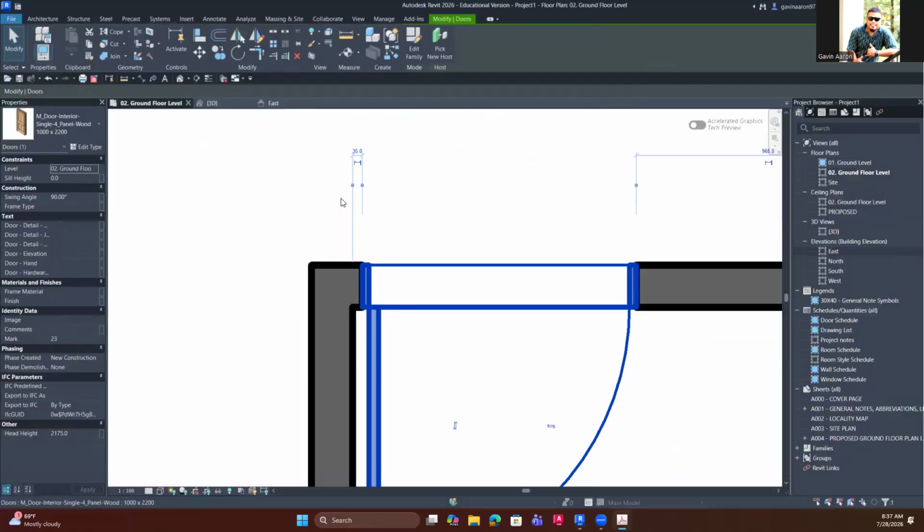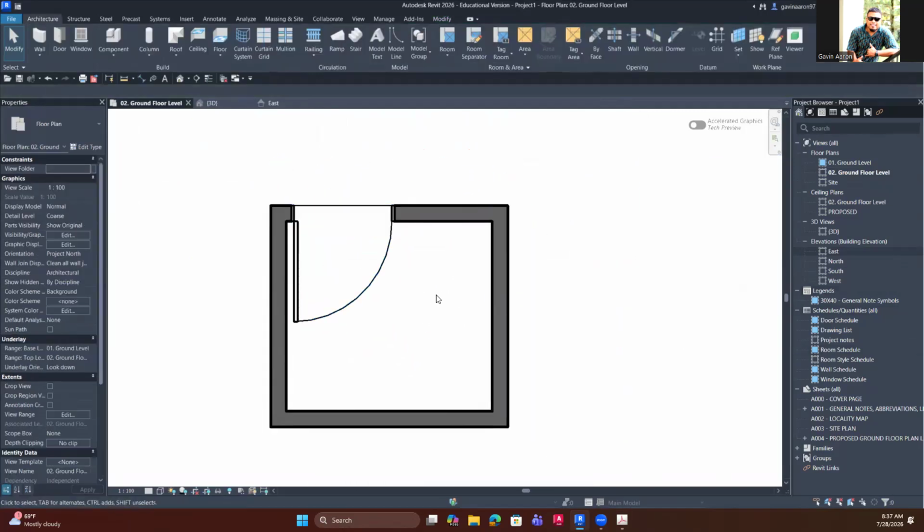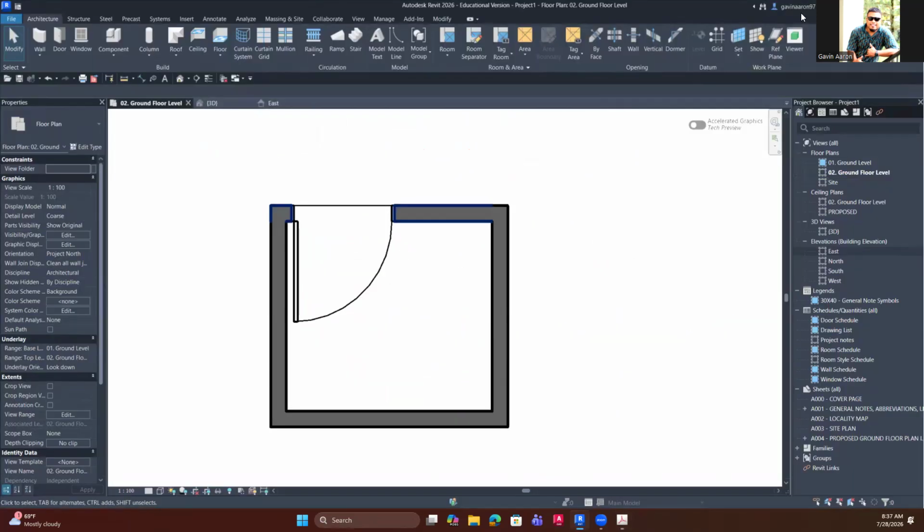So we can select this door, then you see that our door, it's offsetting from the exterior wall by 200. So we can select on the door, you can move this grip of dimension, you just put it on the other side where this wall is, the exterior, then you can write that 200. It's going to automatically move that.